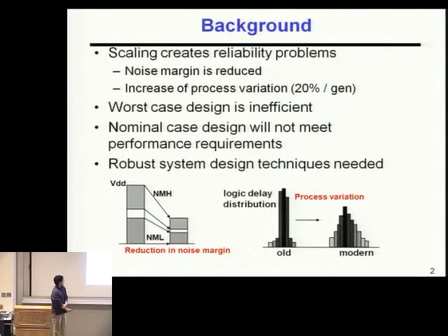In a current 32 nanometer technology, the channel dopant has an average of around 3.5 boron atoms, so some devices have 3 atoms and others have 4, which directly results in a 25% variation. So this process variation manifests itself as a widened delay curve here.